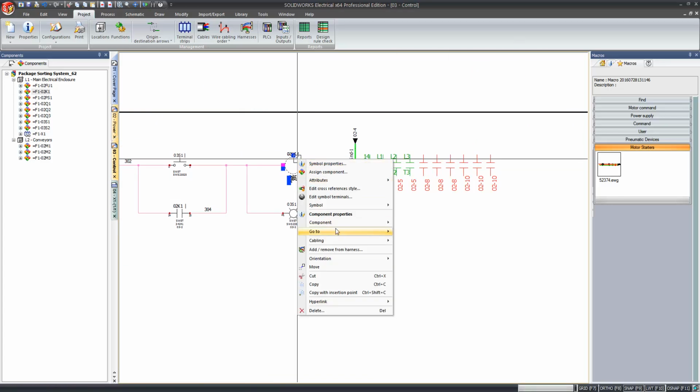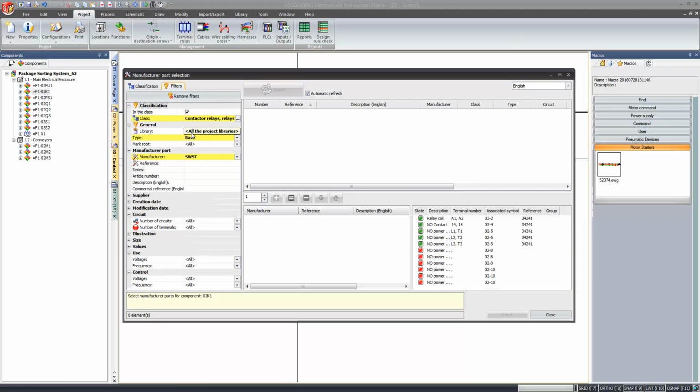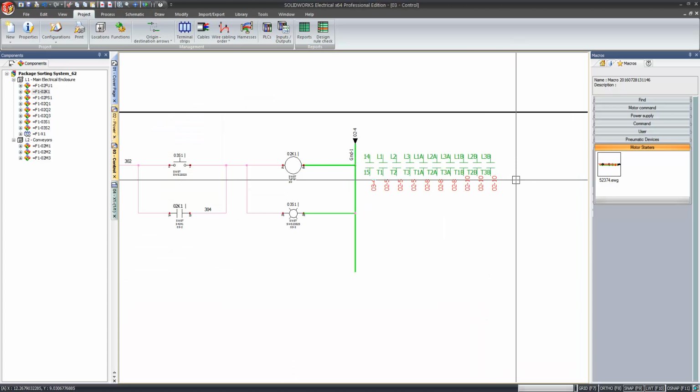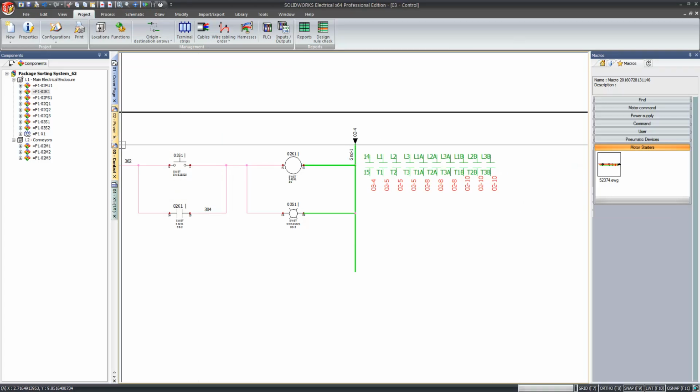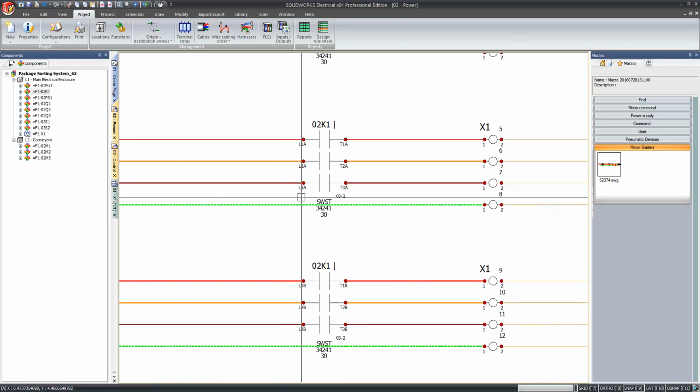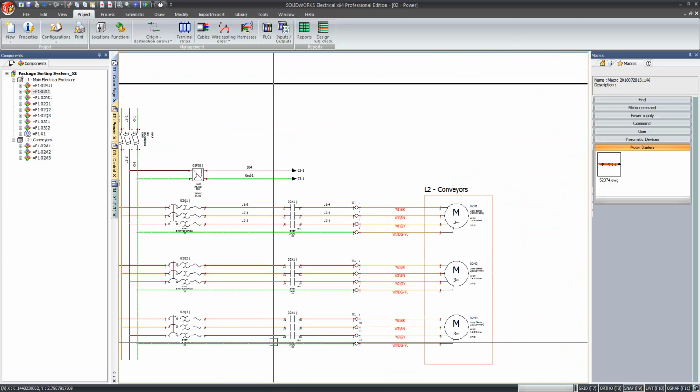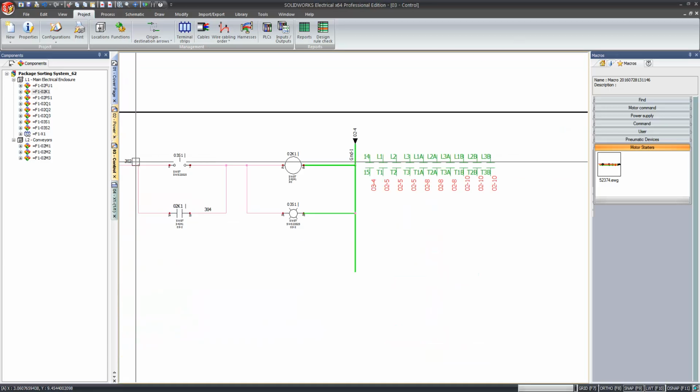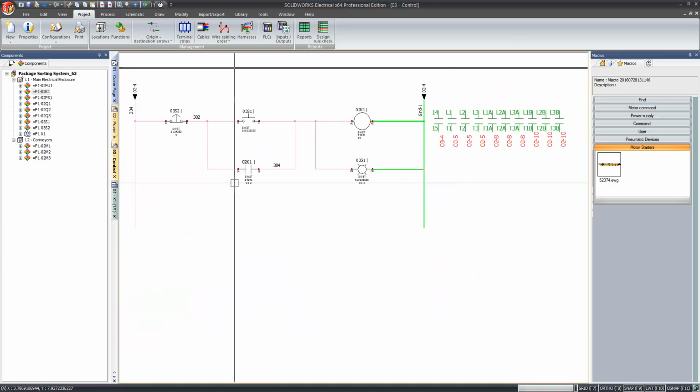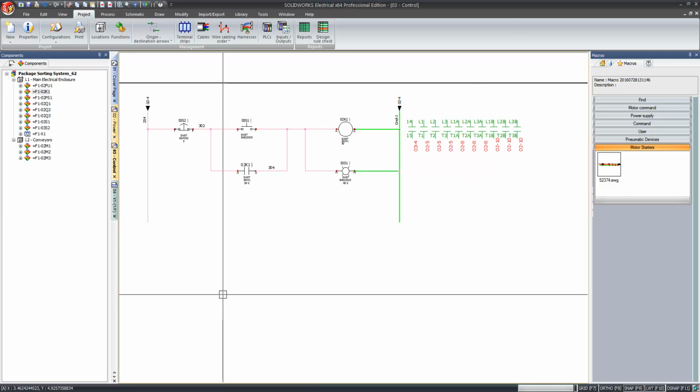So we're going to assign another component here. And it's going to be under type. We need to pick auxiliary. When we do that, we expose our 6-pole auxiliary contactor. My red circuits all turn green. Perfect. Hit OK. Cross references are now all green. And of course, if I go to the power page, terminals are now all labeled. So that part's good.